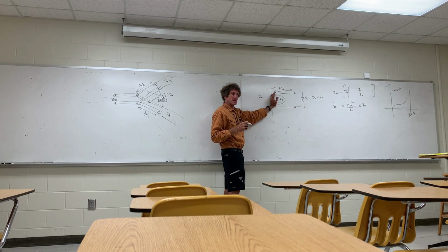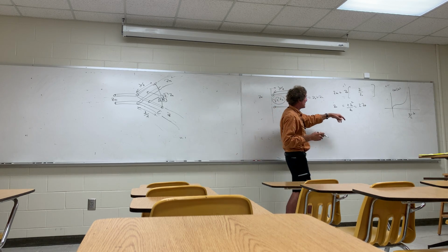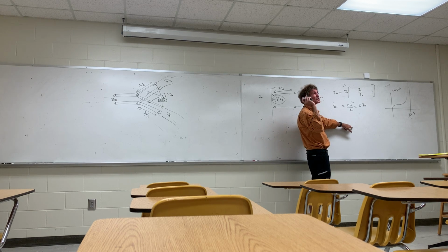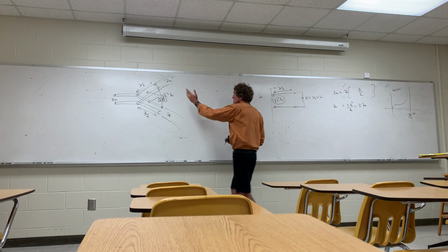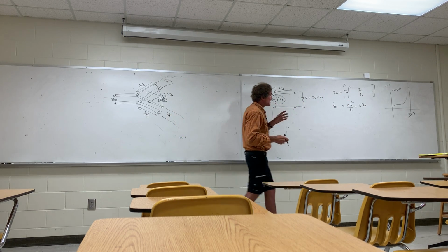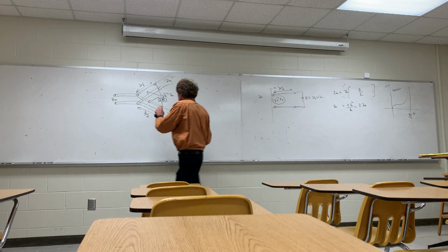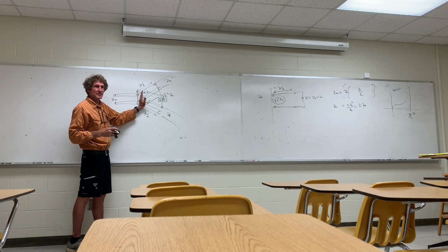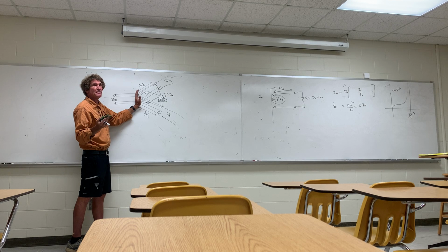Can y'all follow me? I started here, I had Z naught squared over ZL, right? My Z naught is square root of 2 Z naught, actually, right? So you take square root of 2 Z naught and square it, you get 2 Z naught squared. The load is Z naught, that's over here. That's what it's going into, Z naught. So I actually get 2 Z naught as the input impedance here. Just look here. And here. Can you all see that? But they're in parallel. So the net value of the input impedance is just Z naught. You all follow me? That's how Wilkinson's divider works.